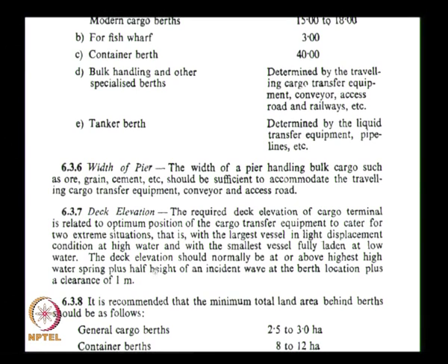So this is related to the environmental condition, that is the high water spring, incident wave and clearance and depth of the deck, geometrical, whereas what we have discussed here is depending on the cargo transfer equipment. So your cargo transfer equipment should be able to access the vessel in various tidal conditions. So considering that you have to fix the deck elevation, but prime consideration is this only. Then you have to design the cargo transfer equipment according to this.